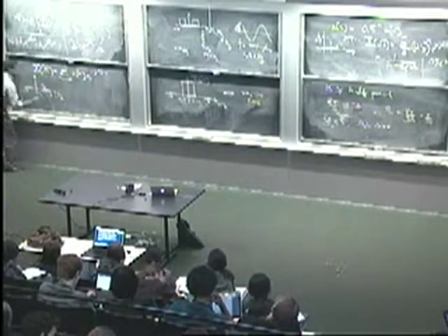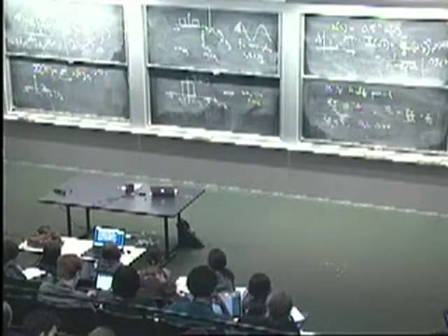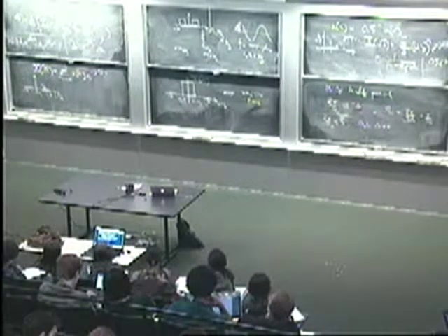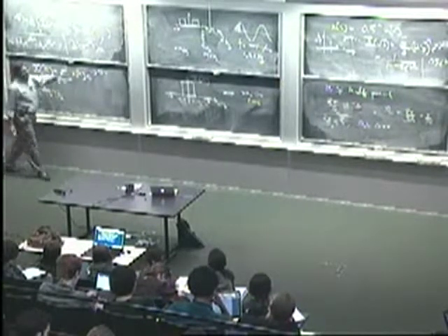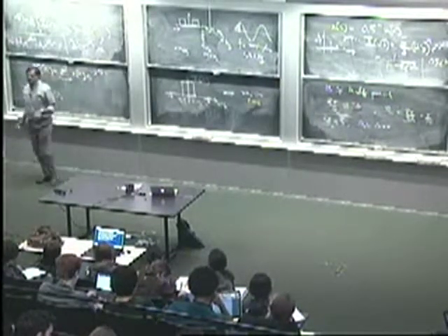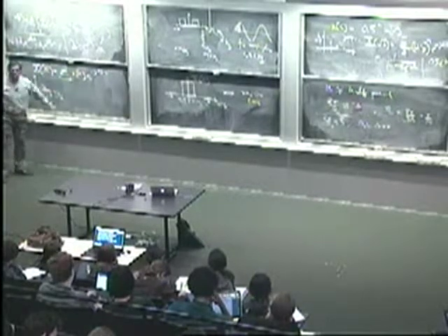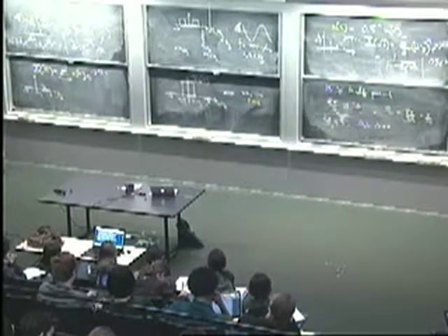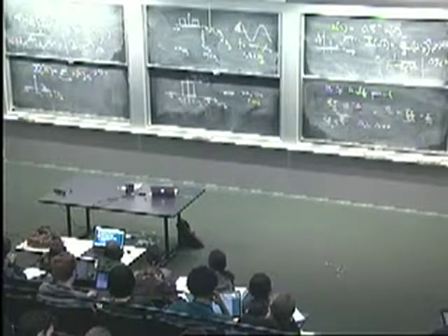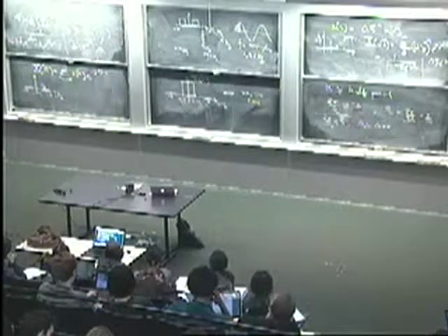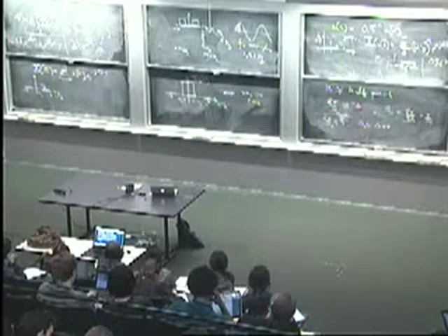So you'll form a little grid, and it's on that grid of points that you want the DTFT. That's the only practical thing you can do. You're not going to compute it at all omega outside of toy examples like that. So if you had a numerical sequence collected in the lab, for instance, this is what you'd be aiming to do. What's the other thing that's likely to be the case if you've got a numerical sequence collected in the lab?